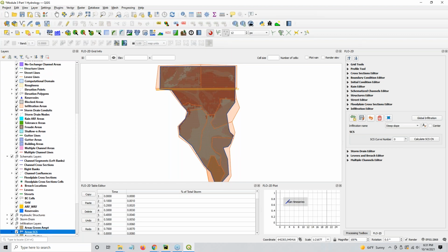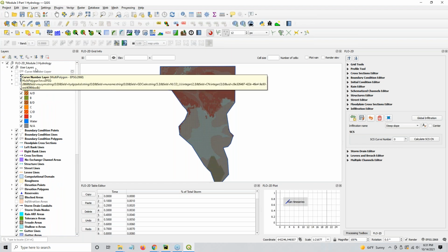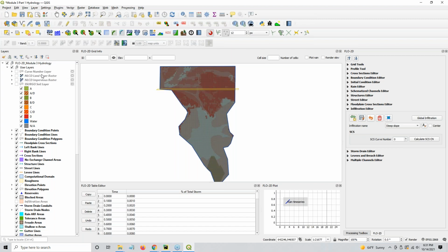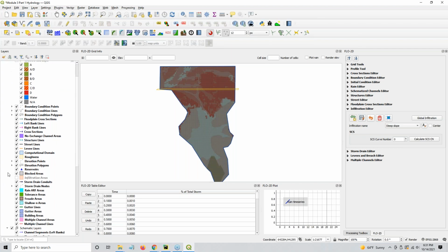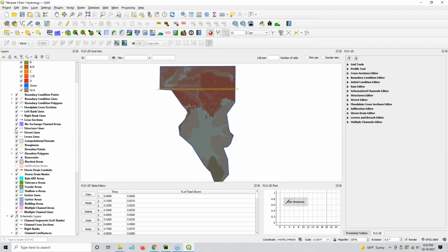So originally my infiltration data came from some polygons. That was a different method of calculating infiltration. This is coming from an external layer. And I've actually had a lot of problems with this. And this system has solved all of the problems I had with getting a good curve number generator and calculating a good curve number from this data. So that's pretty cool. So that's your curve number being calculated. That's now finished. Now let me show you what I did.